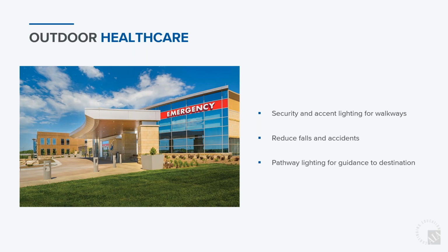Cutoff distributions and shielding are used to control such issues. So we really want to make sure that we're designing our outside light to provide the proper amount of foot candles for security, but not too much where we're intruding into patient rooms, or somebody walks up to the hospital and you've got these glare bomb bollards just sitting out there that are really uncomfortable. We want to carry that same element of thought and design that we apply to the inside to the outside space of the hospital.